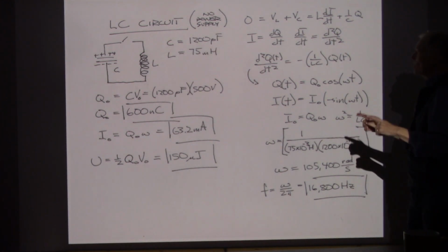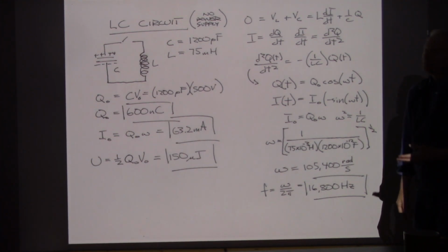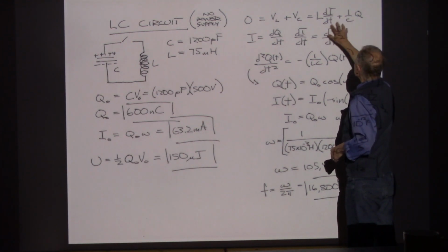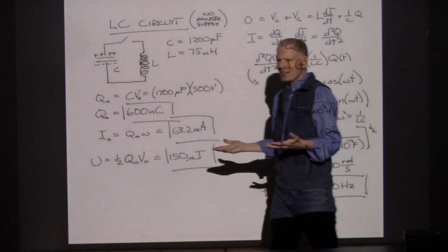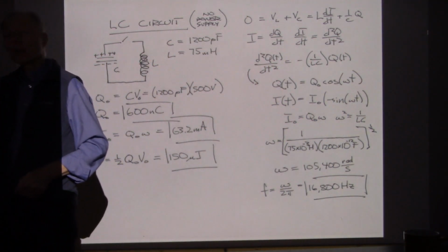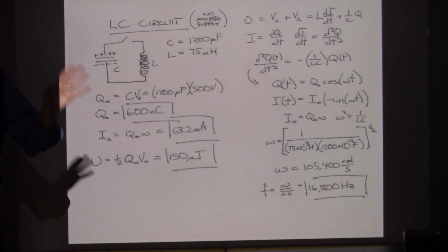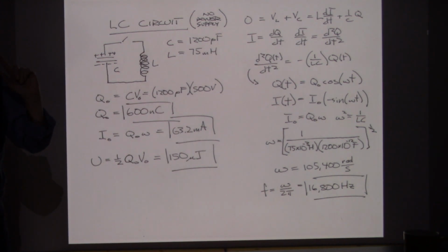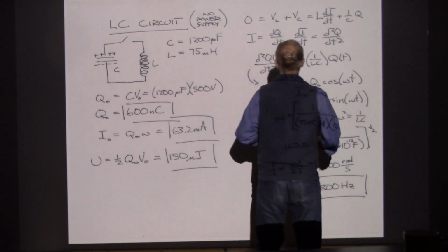And what that produces for us in a circuit is a voltage drop. So this is the voltage drop for the inductor, this is the voltage drop for the capacitor. Now I add those together. Now you might be thinking, well, wait a minute, I can't have just voltage drops. And so what happens is one of these voltage drops at any given time actually has a negative value to it. So the inductor and the capacitor can serve either as a voltage drop or as a voltage drop in the opposite orientation, let's say. And so they can keep the circuit going. Let's see mathematically how that works.